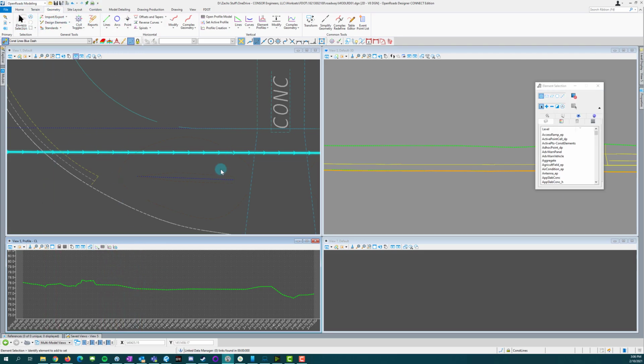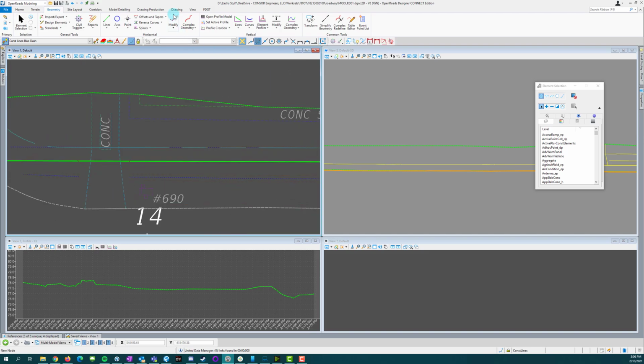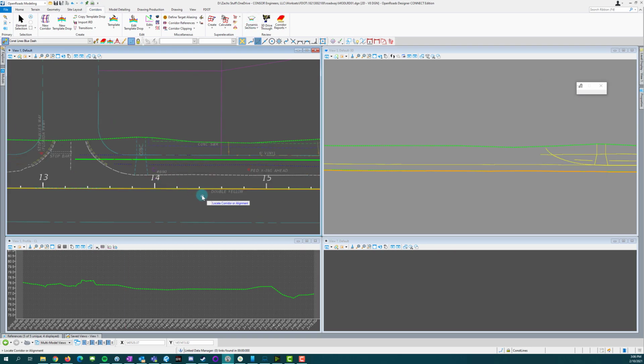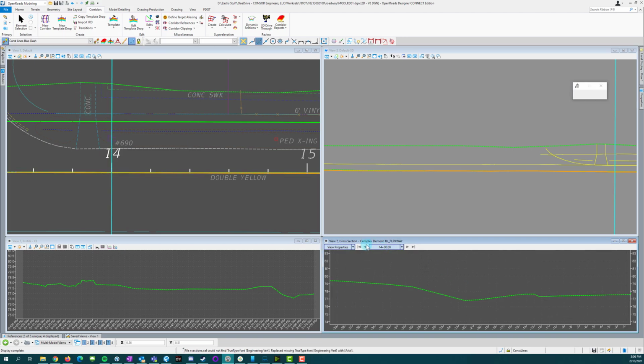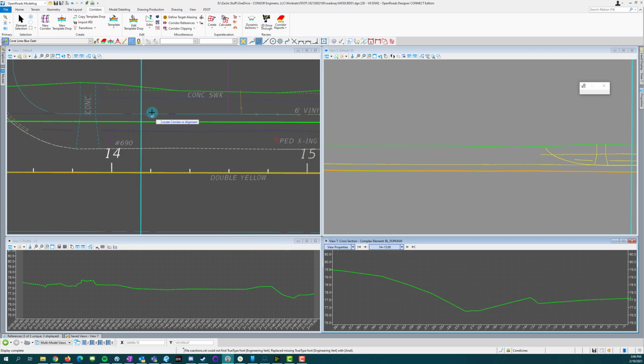And we can maybe look at a dynamic section here using this. I'm going to go left like 50 feet, not even that, 40 feet, and then I want to go right 0, go to 14, 5-foot interval. We can come down here and look at that. 2-foot exaggeration. So we can kind of see that typically all the water is coming from the right-of-way line into this ditch.